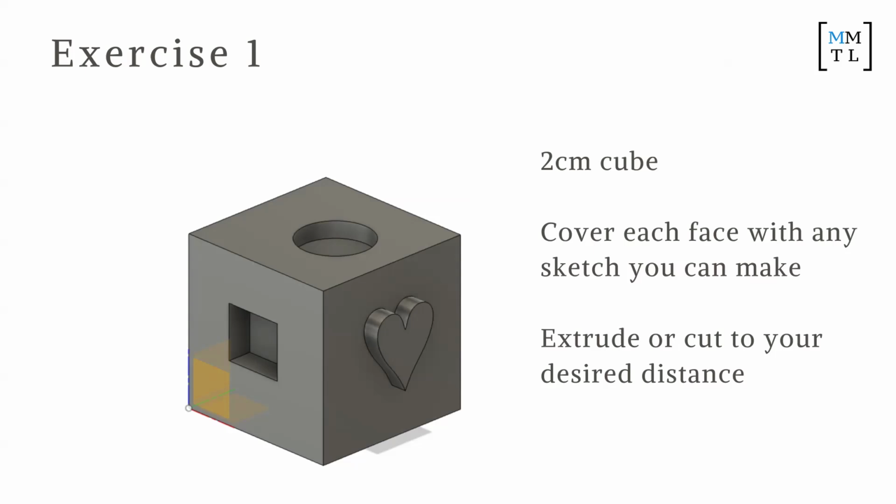If, for example, you've extruded once already and you want to modify that extrude, go to the parametric timeline and click on the extrude, and you can modify what you did. That's particularly useful. See if you can remodify one of your old extrusions. Double click on it, and the menu comes up, and then you can modify it.